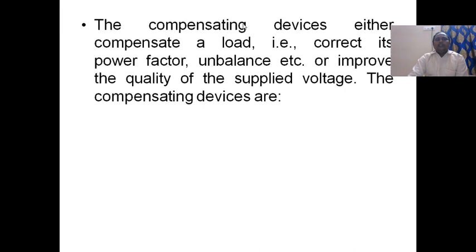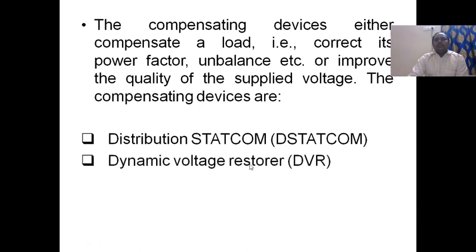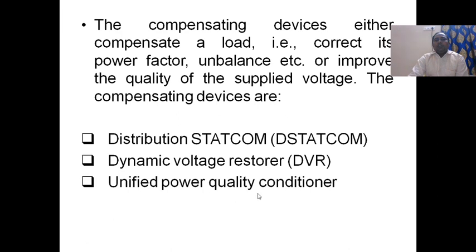The compensating devices either compensate a load, either correct its power factor, unbalance, etc., or improve the quality of the supplied voltage. The compensating devices are the distribution StatCom, that is nothing but DStatCom, the dynamic voltage restorer, and the unified power quality conditioner, that is called UPQC.